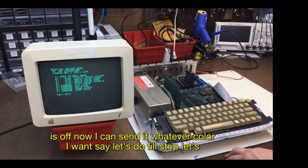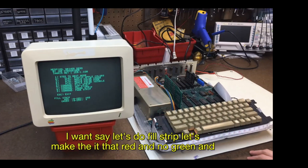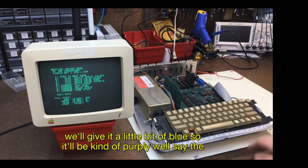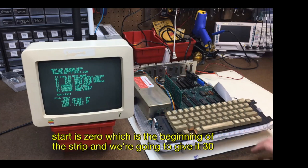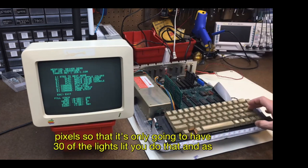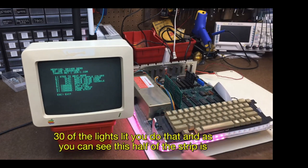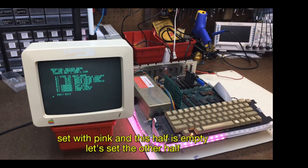Now I can send it whatever color I want. Say, let's do fill strip. Let's make it that red and no green, and we'll give it a little bit of blue, so it'll be kind of purpley. We'll say the start is 0, which is the beginning of the strip, and we're going to give it 30 pixels, so that it's only going to have 30 of the lights lit. We do that, and as you can see, this half of the strip is set with pink, and this half is empty. Let's set the other half.